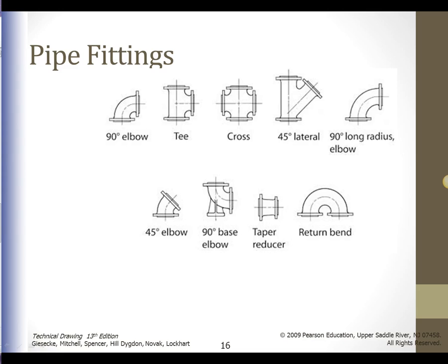These fittings provide branch connections at different angles to affect different directions and sizes. You could actually have a bigger pipe coming in, a smaller pipe coming in, and a bigger pipe coming out. For example, you have a 12-inch coming in and maybe a 16-inch coming out. Fittings are available with threads.